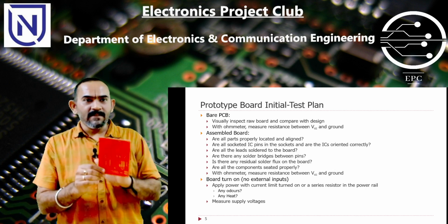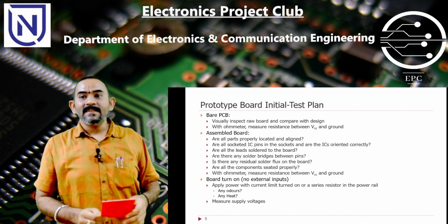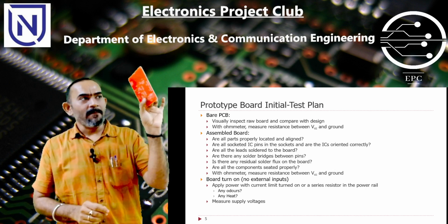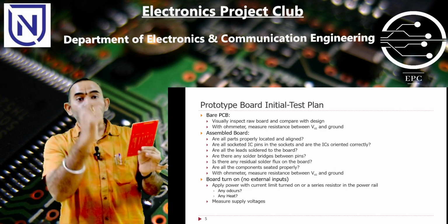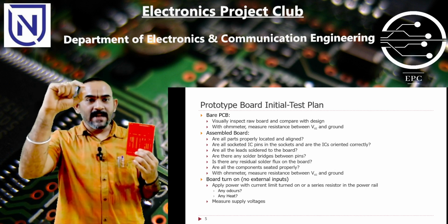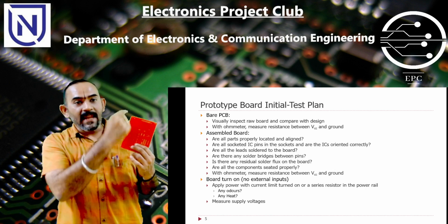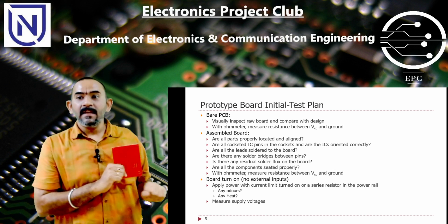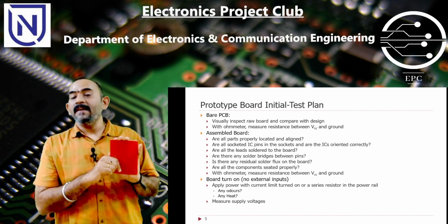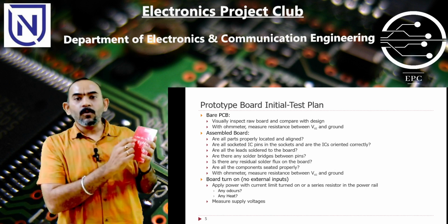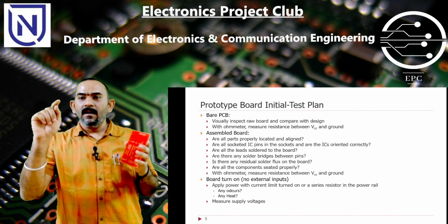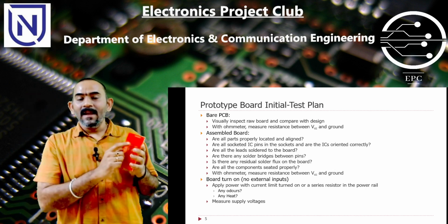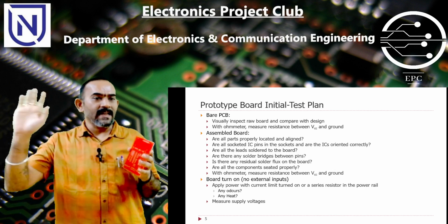Okay, if everything works fine, then we can go and start assembling the board. Now it can so happen when this is fabricated, two closely lying pads can internally have a short. That can be found out in the bare PCB mode itself. Now why is it necessary? Assume that two closely lying pins were, say, one VCC and another some IO pin, to which you are not supposed to give a high current.